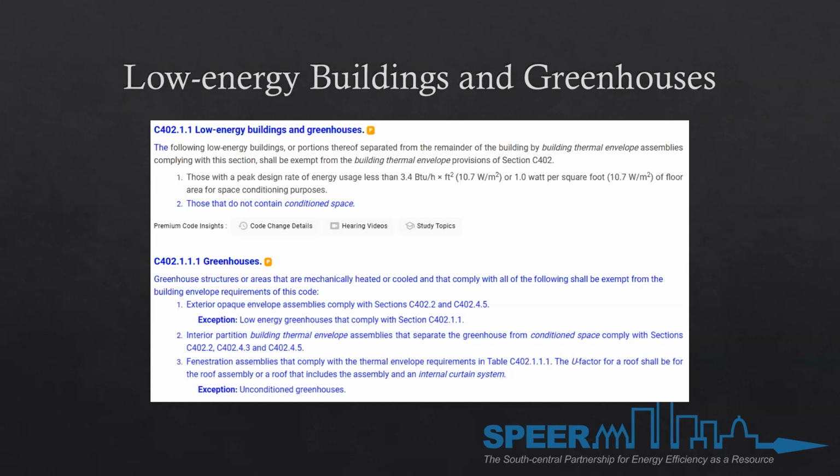It doesn't matter if it has 65 lights in it. You can do a lighting schedule and get that approved through the city. But as far as energy code goes, you don't have to comply with the energy code if it's not being conditioned. But even adding window units, that's a plugged in appliance that can be removed, not a permanent fixture. So now is it considered permanently conditioned? It was a tough call.